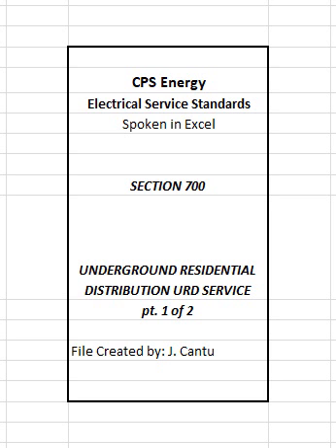703.1 Transformer pads. Pads for single-phase transformers up to 167 kVA shall be precast concrete and shall be furnished by CPS Energy. In special cases approved by CPS Energy where larger transformers are needed, transformer slabs will need to be constructed in accordance with CPS Energy specifications. Customer shall coordinate with the CPS Energy customer service representative for more information.